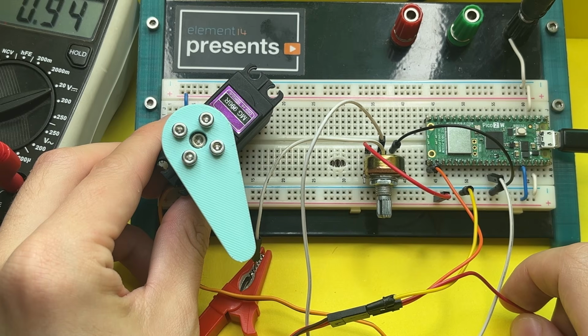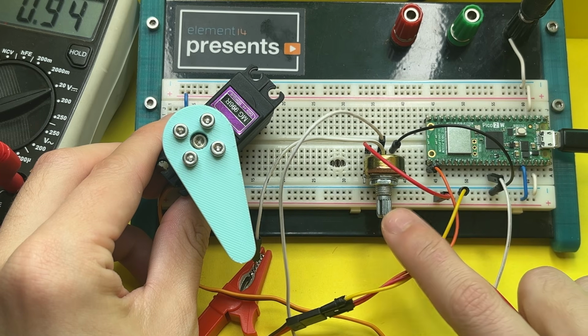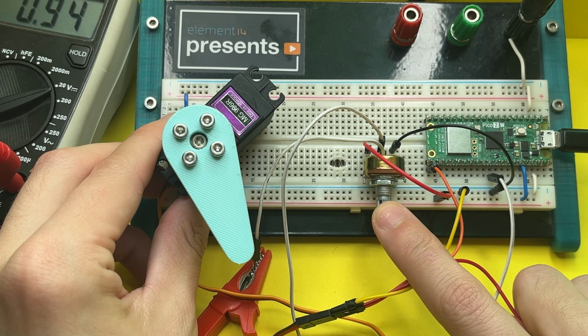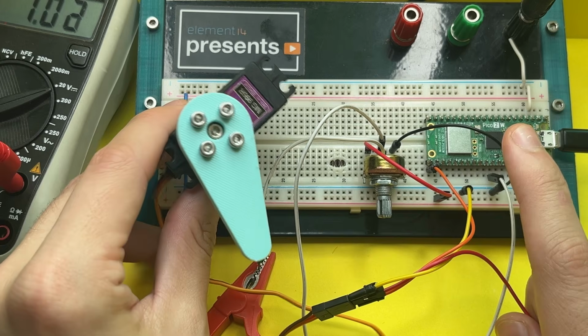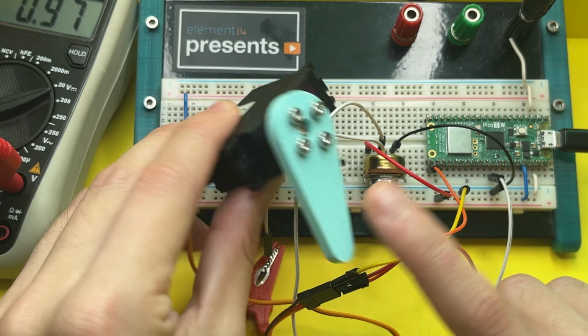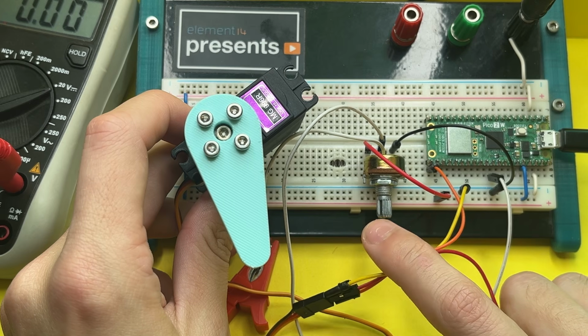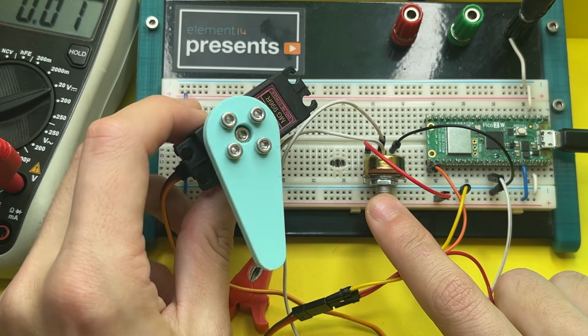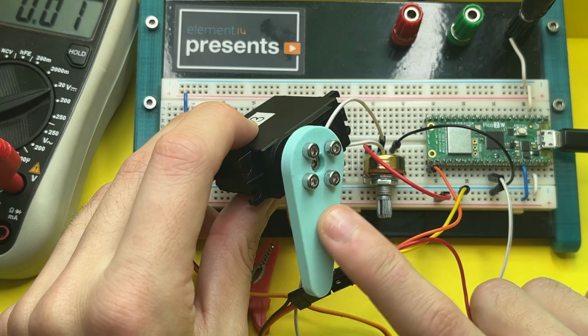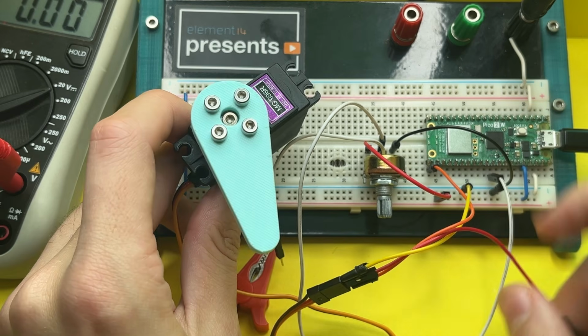Let's see how this looks in practice by us controlling this servo motor using our potentiometer. Now it's time to close the loop. So what that means is using this sensor, getting those measurements, doing something with them, and sending that data then over to the actuator. Why is that called closing the loop? Because we have a full control loop. So we're using the measurements from this sensor to actually interface with this actuator through the microcontroller.